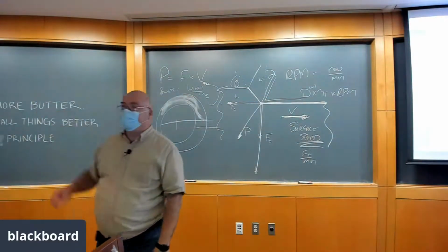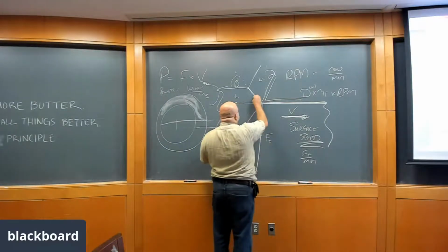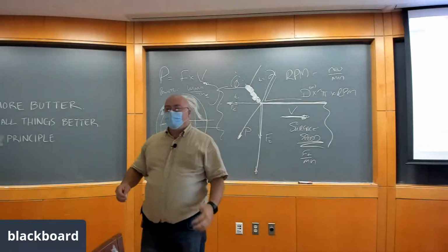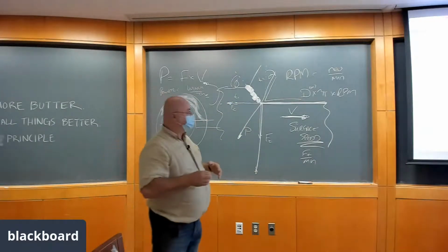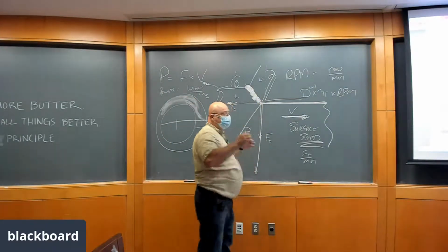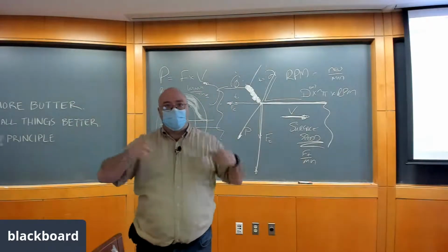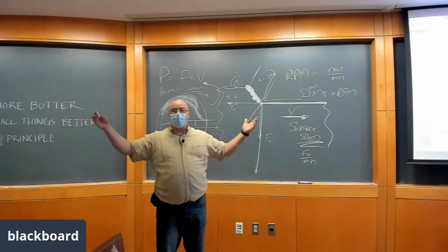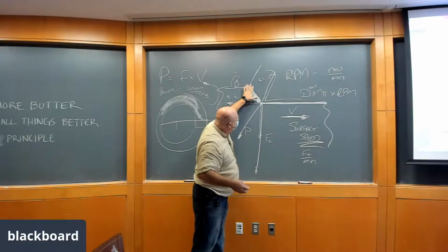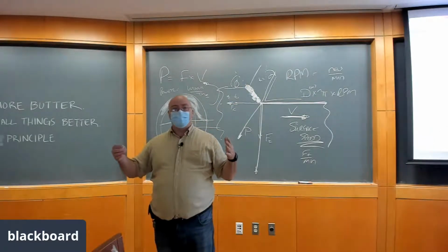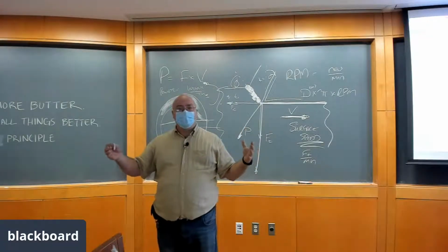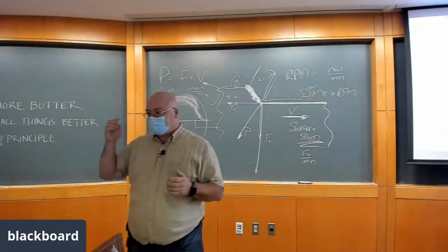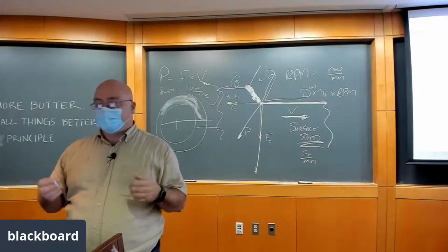The force depends on everything else that's going on in that picture, and it especially depends on the transition that's going on here, where it was workpiece and now it's chip. Would you be willing to believe that there is a lot of energy in this plane when we transfer from workpiece to chip? The bit of the workpiece over here has no idea that it's about to be a chip. It's just bebopping around, living its life. And then all of a sudden it slams into this shear plane and gets changed. It's sort of the change in life, where you get smashed up against something and you come out a different shape. So that happens, and we get chip flying off. That's pretty cool. I think it is.